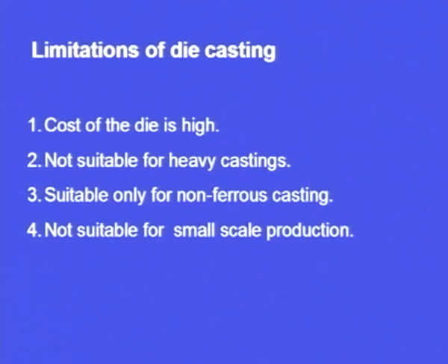These are not costly, but here we are using some special steels which are very costly, and even to make this die we have to put a lot of effort. To machine the die is very difficult. To make the die is very difficult. We have to put lots and lots of effort, and it is not suitable for heavy castings. Big castings cannot be made by this die casting.